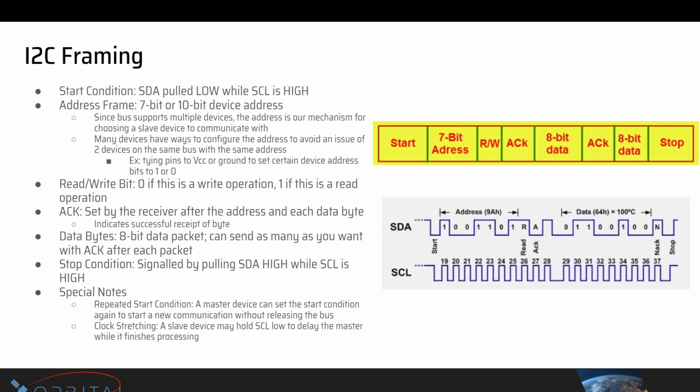You remember how the master is the one sending the clock signal. So while this clock signal is being sent, if your address wasn't mentioned, the other devices are just ignoring and waiting for the bus to be released.